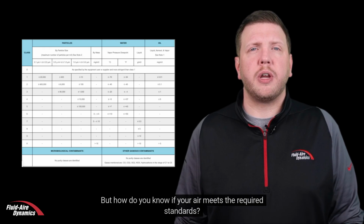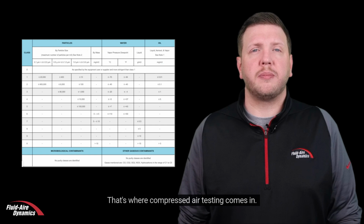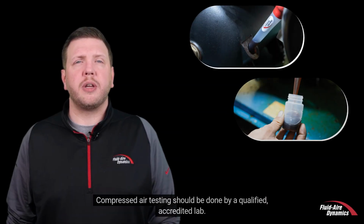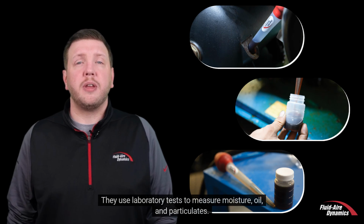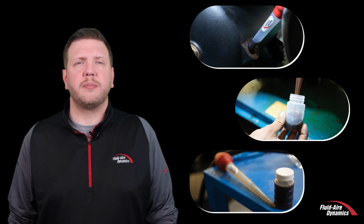But how do you know if your air meets the required standards? That's where compressed air testing comes in. Compressed air testing should be done by a qualified, accredited lab. At Fluid-Aire Dynamics, we work with Trace Analytics, a trusted leader in compressed air testing. They use laboratory tests to measure moisture, oil, and particulates.